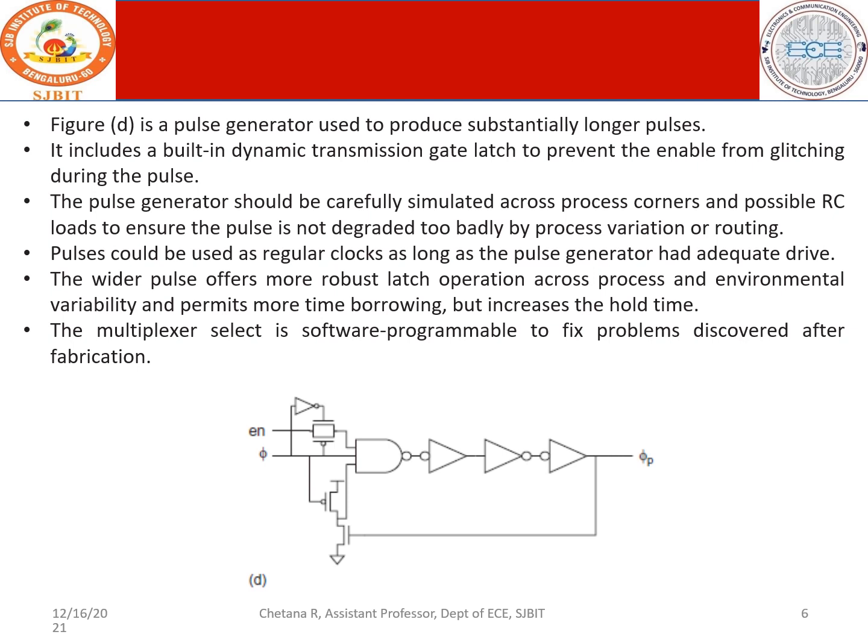So the pulse generator should be carefully simulated across process corners and possible RC loads to ensure the pulse is not degraded too badly by process variation or routing.